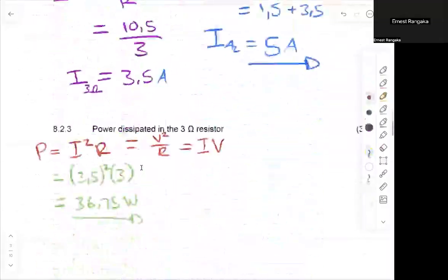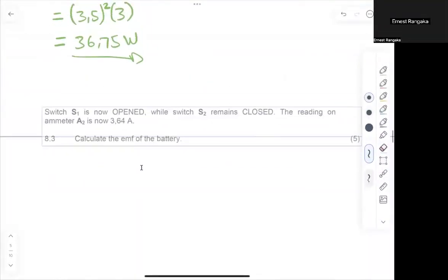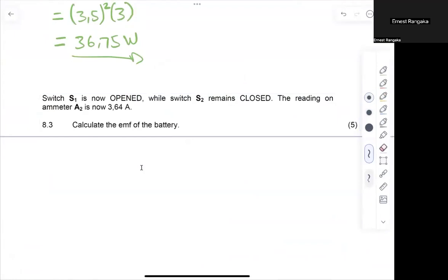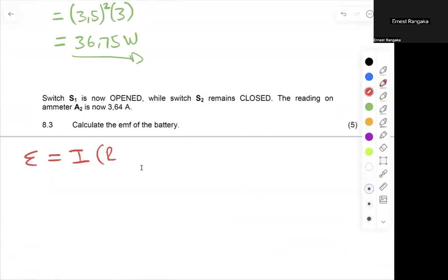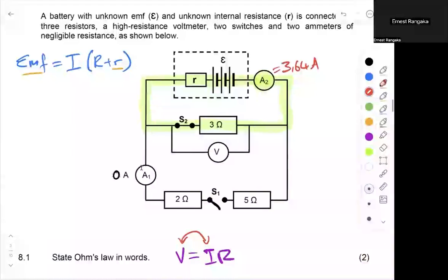So let's first start with the information that's been given to us right now and use that as our step 1. Let's quickly write that equation down. We've got EMF is equal to I into (R + r). Let's substitute what we do know about this. For the equation as it stands, let's call that equation 1.